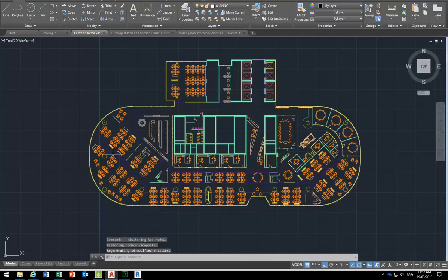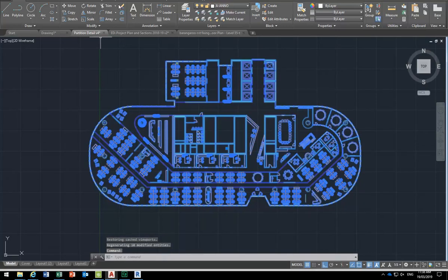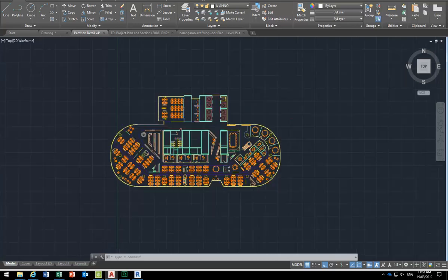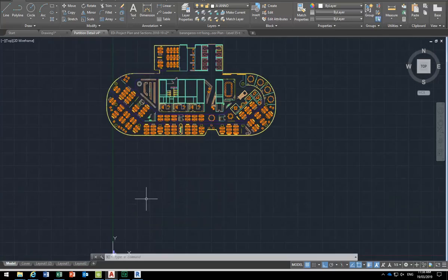So then to work on it though in this file, remember I inserted it as a block, so I just need to explode that. And that's okay. Later you'll see you may want to have those things split across different files, and that's when you can look at XREFs, but maybe we'll go further into that next week. It's not required for your first assignment, but it's something you've got to know about. So that should do it. So, yeah, I'll finish there.